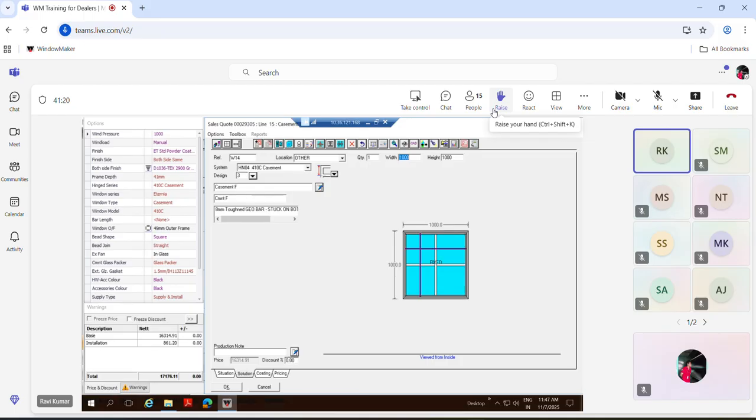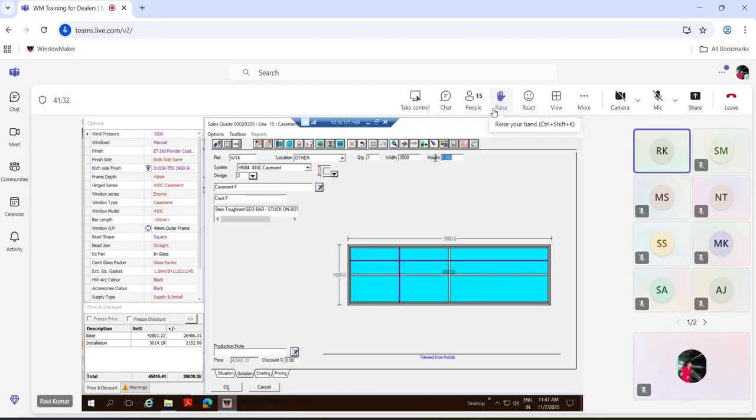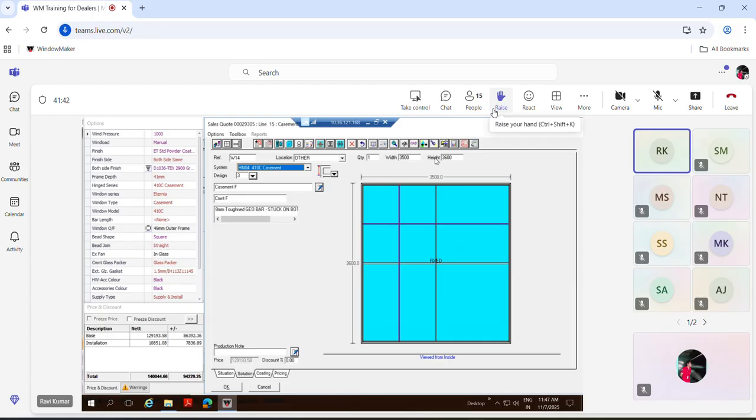For fixed part you can consider 2000. Like if your width is 3500 and height is 3600, maximum height you can consider in this series is 12 feet. But for this height, mesh is not feasible. Mesh is only feasible for 3 meter.